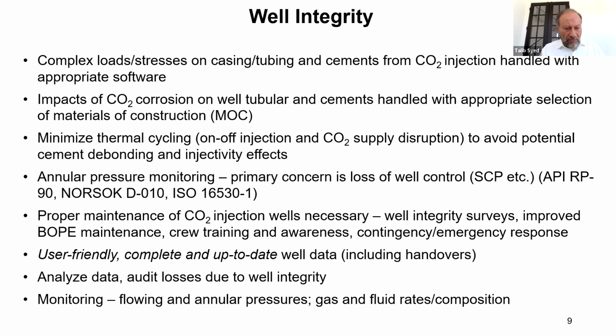Proper maintenance. Have good, complete, user-friendly data. Analyze the data and find out what are the reasons for loss of well integrity. And like I stated before, monitoring is very important. CO2 is not explosive, like I mentioned before. Fires are not a concern, but asphyxiation is, since CO2 is denser than air.